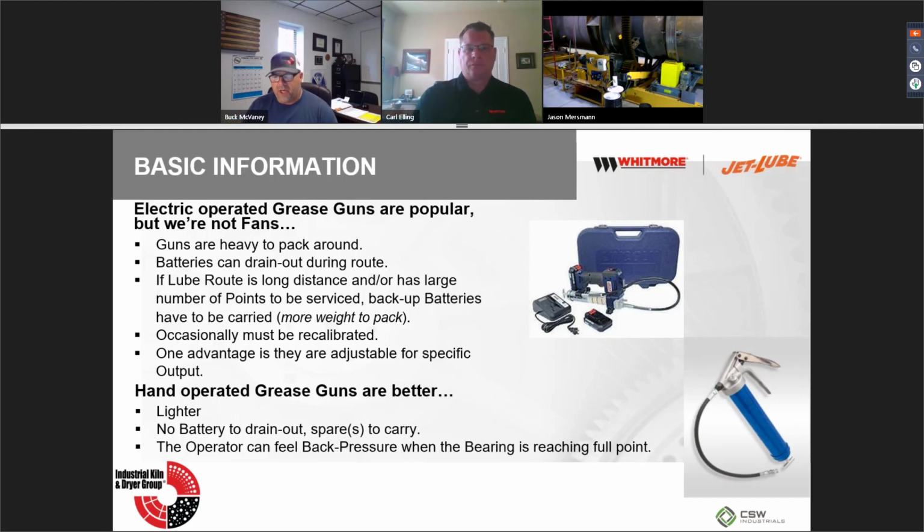And sometimes it's just a cultural change, and those are the hardest things to do, right? To change the culture, because we're just so used to, this is the way we've always done it. And that goes on down the line. But very important. I understand the feeling on the electric, but I think it's really critical, if you're using either electric or manual, to understand what one shot is, what one pump is. What does that mean? To understand what the amount is, and the frequency. Those are very important to know, without it just being some random number, 5 pumps is what it takes, without understanding what 5 pumps represents.